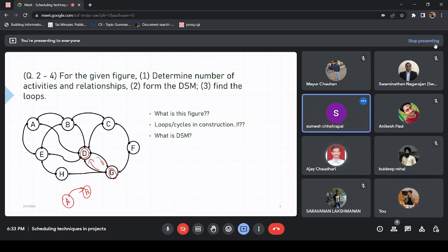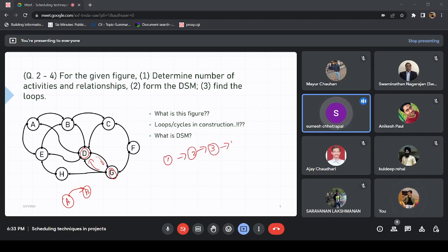For the construction of a cooling tower, sir, a natural draft cooling tower, we are constructing the shell. It is a continuous work and it is a cyclic work. Every lift will be constructed. In that lift, sir, there are four processes. First, we have to tie the reinforcement. Secondly, we have to do the shuttering. Third, we have to lift the jump form. Fourth, we have to do the concreting. So all the activities are related to each other.